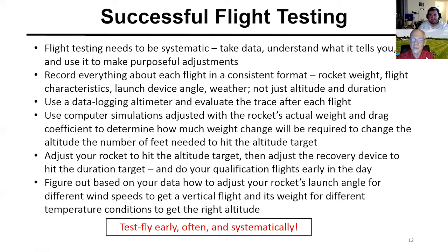So flight testing is testing. It's taking data, understanding the data, understanding how to adjust for what the data tells you. Flight testing then repeats the flight and verifies that what adjustment you made achieved the effect you intended. And if it didn't, what did you need to change again to get onto target? This is a systematic, step-by-step process. Take the data, understand the data, use the data, change something if necessary, fly again. Do it again and again and again.